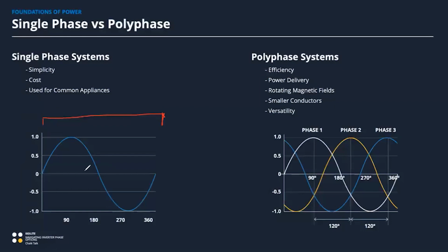The net result of that is if you look at this signal, there are periods of time here where there's really no voltage on the line, which means that there's really no power that can be derived from that signal. So, generally, high power motor loads and other loads take big drinks of power at these peaks, and they can't really get any power here. And that really drives down the efficiency.